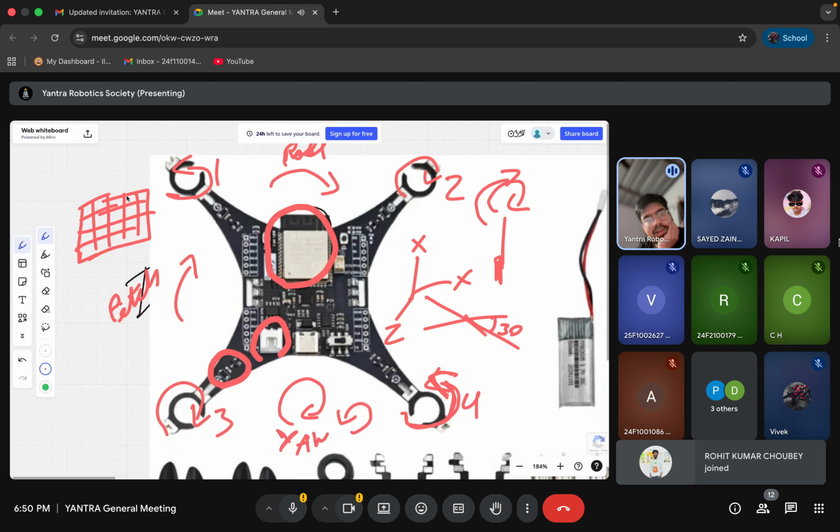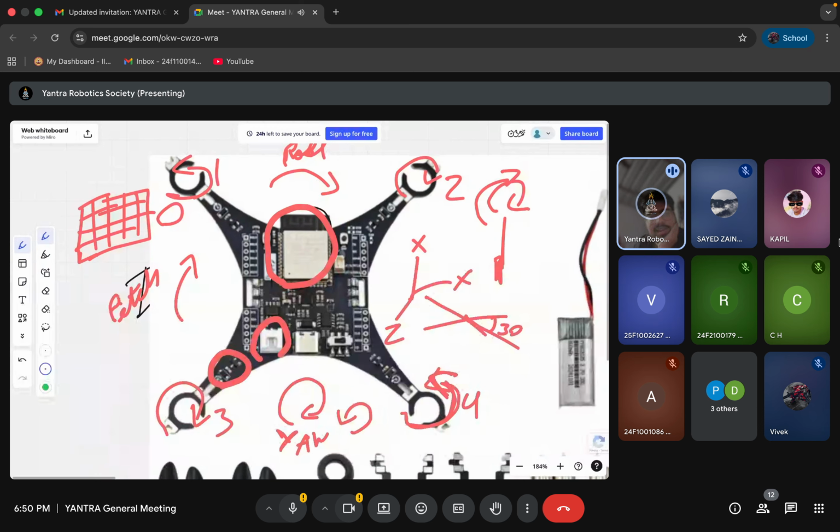An optical flow module has both sensors, optical flow plus a lidar, which gives the distance from the ground. With these two things, it can calculate how far above the ground it is, and it knows how far back, left, or right it is from its origin.